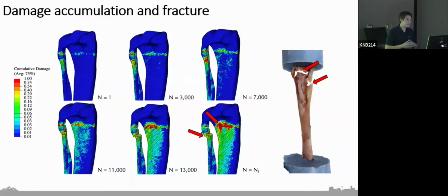That's what I was wondering, if you just take an arbitrary point, and put a couple of strain gauges on there, which would be quick to do, and then not use those as input for the optimization, but then see, does it predict strains at some other random places as well? That's a good idea. One thing we would benefit from is that we would have to load fewer bones if we do it that way. We could load the same bone, read off the strain outputs, take half of them, use that for the model, and then check it on the other half. So it's a good idea.